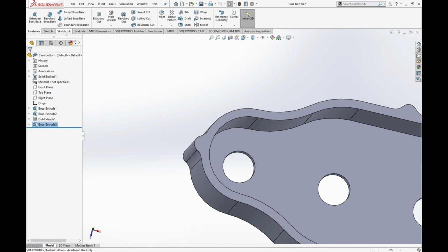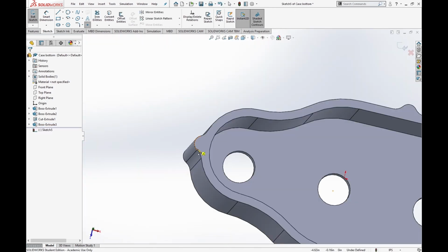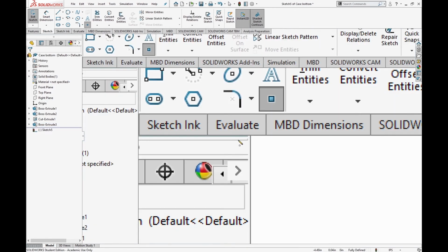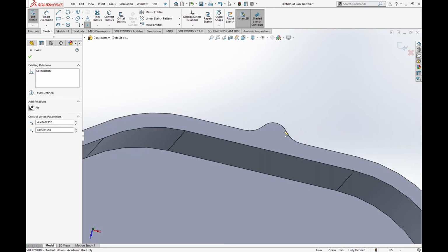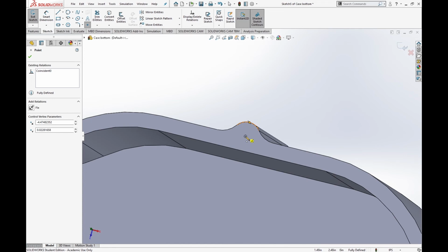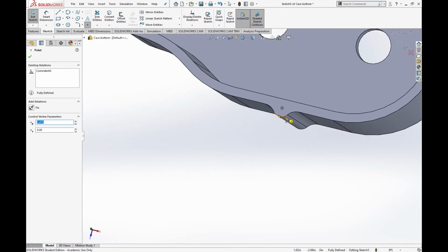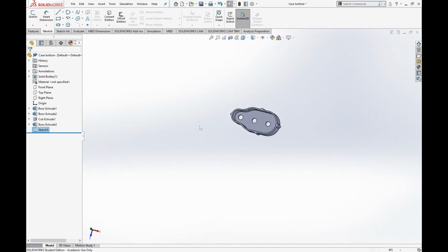So what I like to do is I'll just do a quick sketch, and I'll put these points on the sketch. So then I can select this top face, and I'm just gonna do point here. Alright, you're not coming out, point. There we go. Point. Point. Last point. Alright, and now I have those points there.